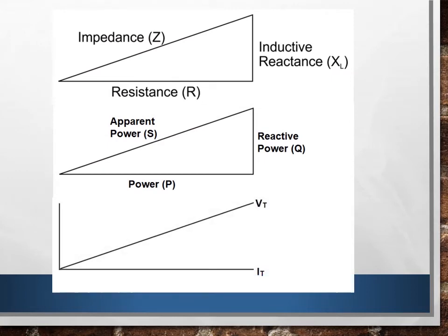When it comes to our impedance diagrams, as well as our phasor diagrams, as well as our power diagrams, they should all look exactly alike. The other thing that will be exactly alike is the phase angle. And remember, my power factor is the cosine of my phase angle.